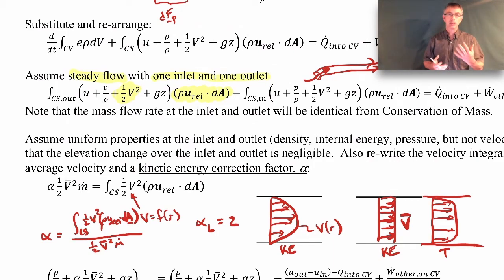You still have the no-slip boundary conditions at the walls, but most of the flow looks kind of like the average profile. It's very blunt-shaped. Again, this goes back to our boundary layer discussion, but it's happening because of all this mixing. If you look at this profile, it looks pretty close to the average already. It certainly looks closer to the average than a laminar profile, which is a parabola.